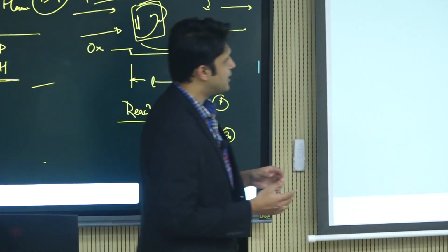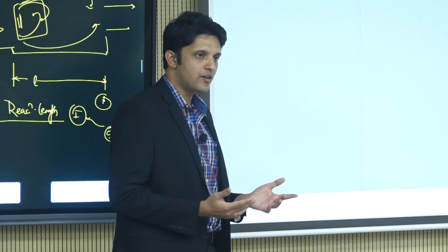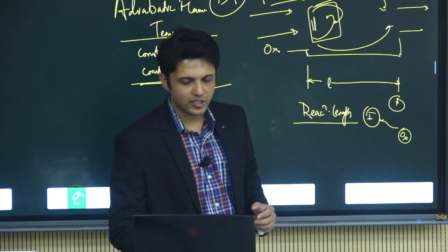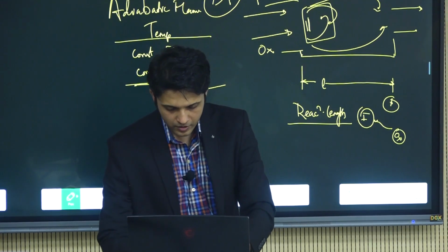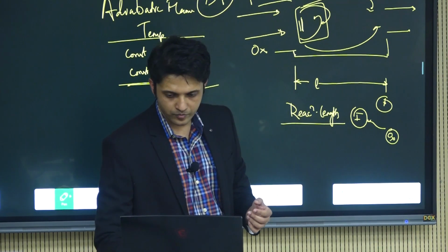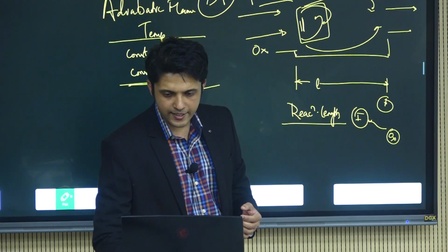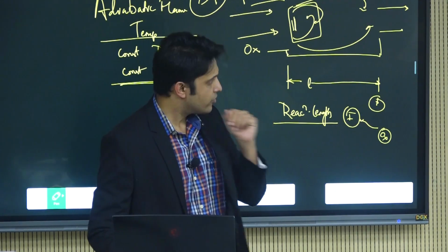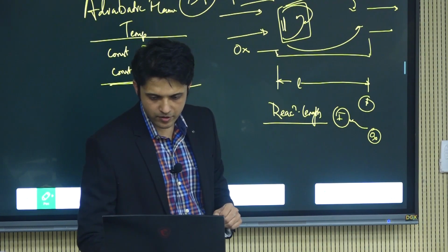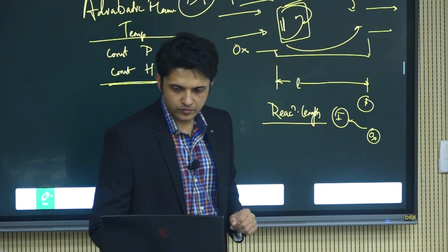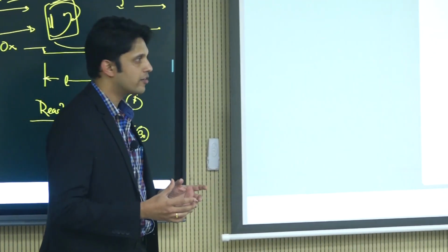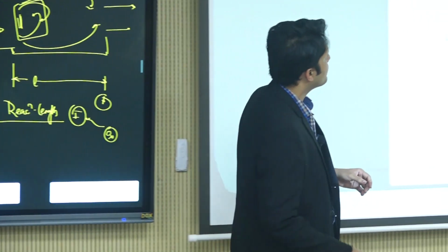But because of incomplete combustion, there might be carbon monoxide coming out, right? So that could be a good guess of some additional species to consider. So let's put carbon monoxide over there, and all the other settings are the same, constant pressure and enthalpy, and let's calculate again. So now we are calculating for a richer mixture, considering some additional products. So what happens to the temperature?